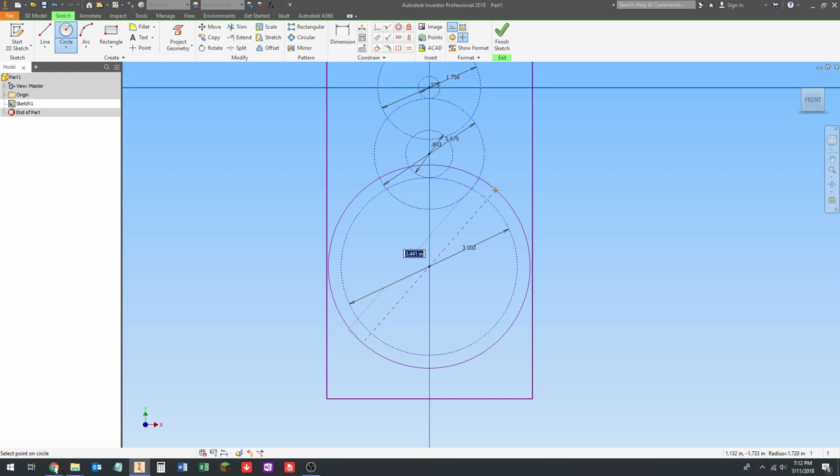Okay. Now the outside diameter of a gear is the same as the pitch diameter of a gear with 2 more teeth. Just to see how that applies in our situation, this is a 60 tooth gear and it's 20 DP. So the outside diameter of that gear is the pitch diameter of a 62 tooth gear. So we're going to put in the equation for that. It's 62 teeth divided by 20.